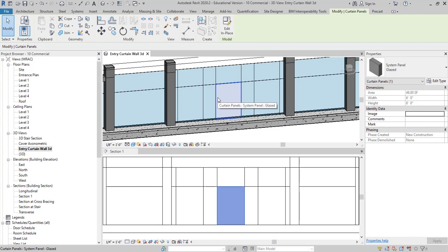So this, we are now currently up to about the bottom of page 438. And the way this works, the door is actually not a door. It's going to be scheduled like a door. It'll show up like a scheduled door. You'll be able to put a door tag on it, but it's actually a panel, and the entire panel will be filled up with door. And so in order to do this, I need to go and get that door.